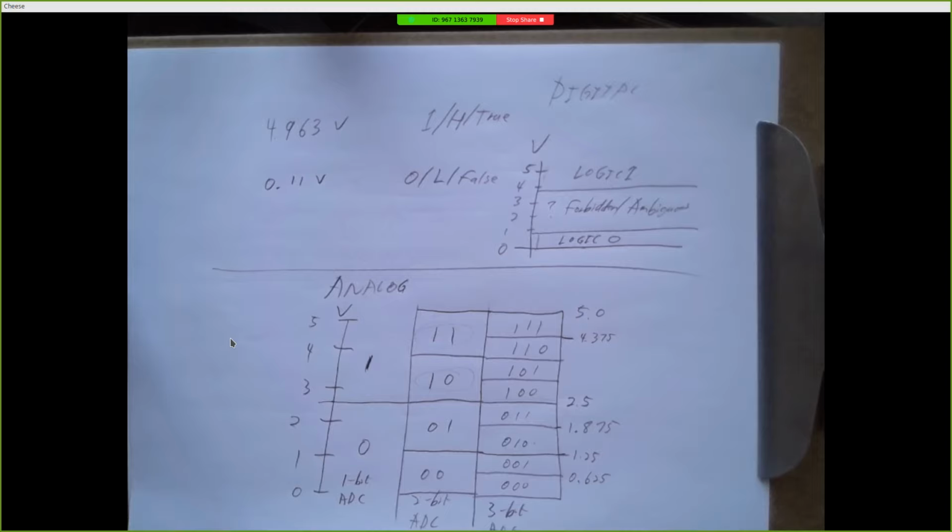And in the case of an effects pedal, for example, at the other end of all of that, we need to go from this digital value back to an analog. So there's a digital to analog conversion process, DAC. We don't deal with that in here, and the PIC processor does not have a true digital to analog converter. But we can fake it. Guess how we fake it? By using pulse width modulation. Alright, but we're just going to talk about analog to digital.